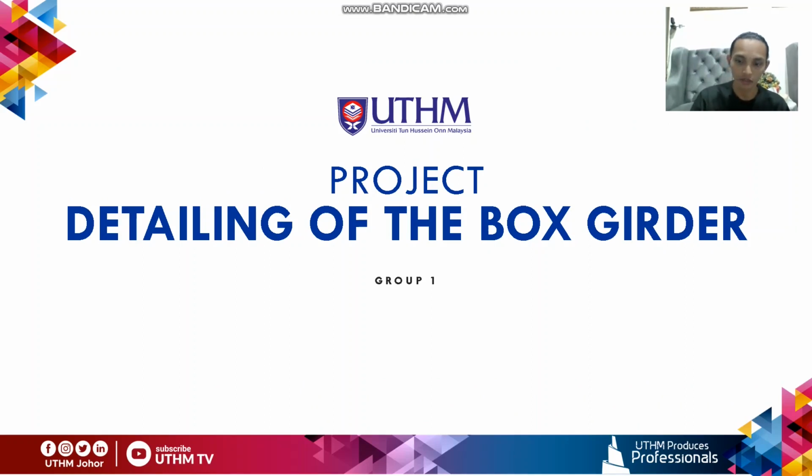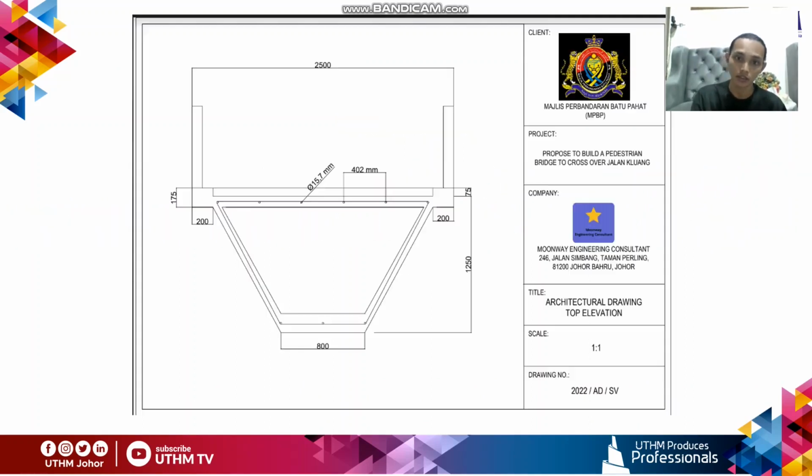Now for the detailing for the box girder. As we can see here, we use a box girder, and there are 9 strands. We are using 15.7 millimeters diameter 7-wire super strand. There are 9 of them, and they are 402 millimeters apart from each other.